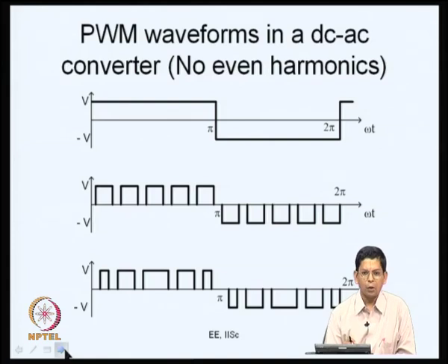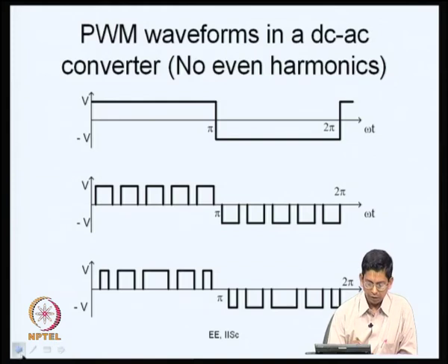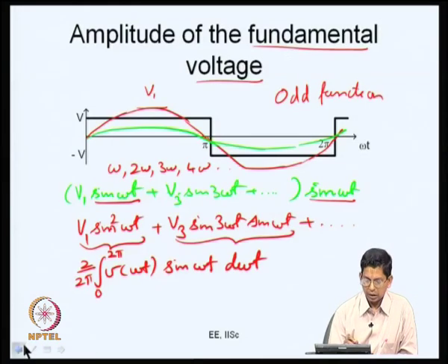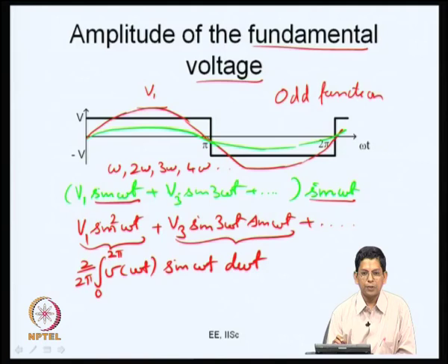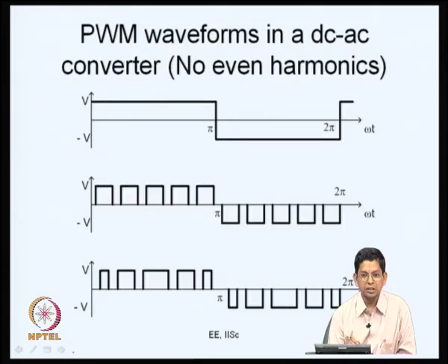Now, let us see how you determine the amplitude of the second harmonic. As we saw a little earlier, we multiplied this whole thing, what is within the bracket represents the waveform, by sin omega t because we were interested to see whether any sin omega t term exists. We wanted to find out the amplitude of the fundamental frequency. Now, if a second harmonic could be present here, we should multiply this by a second harmonic sine wave.